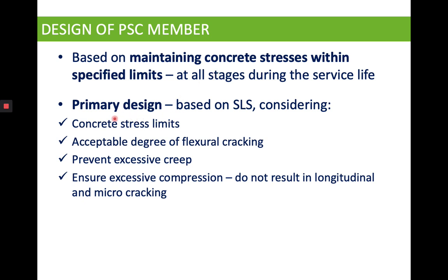You can see here that the primary design will be based on SLS, or the serviceability limit state, and this SLS will consider the concrete stress limits and the acceptable degree of flexural cracking. Then we are going to prevent excessive creep and also ensure excessive compression does not result in longitudinal and micro cracking.